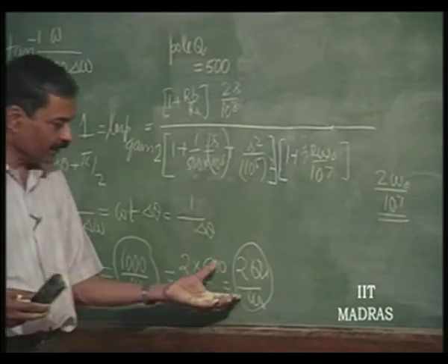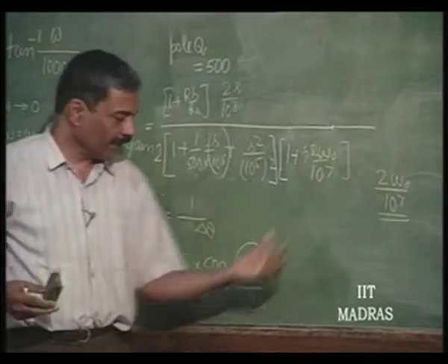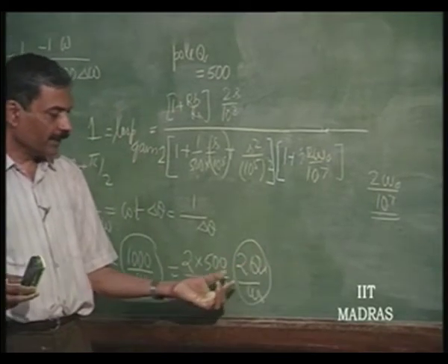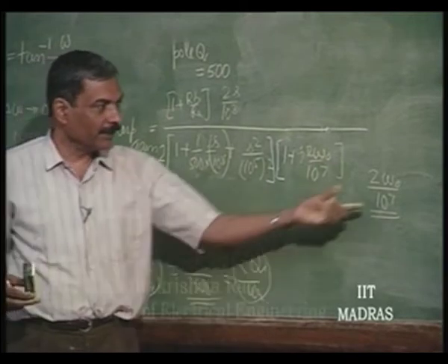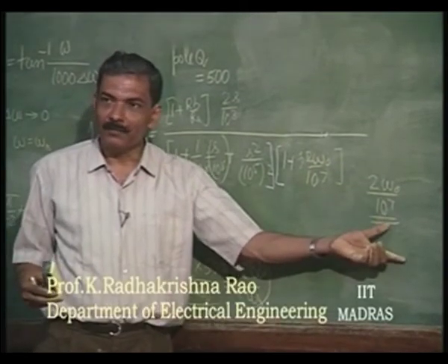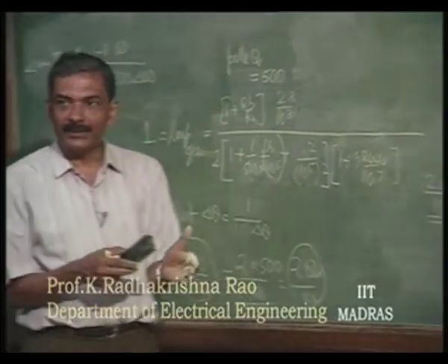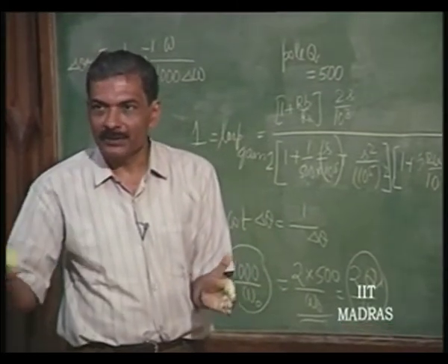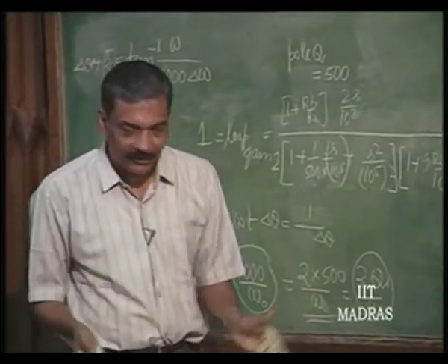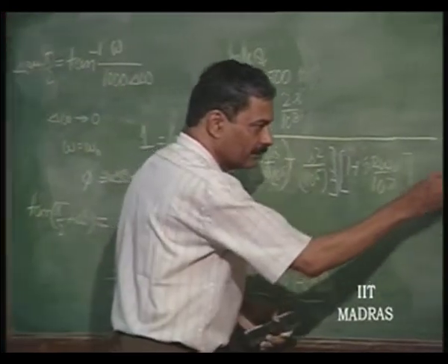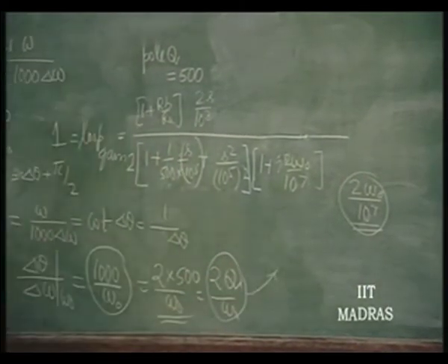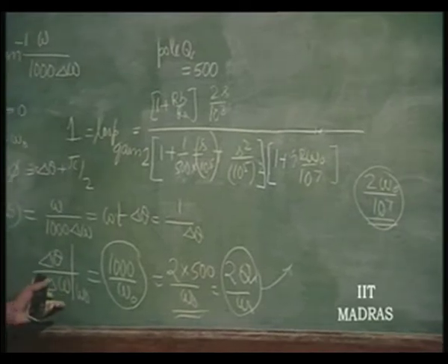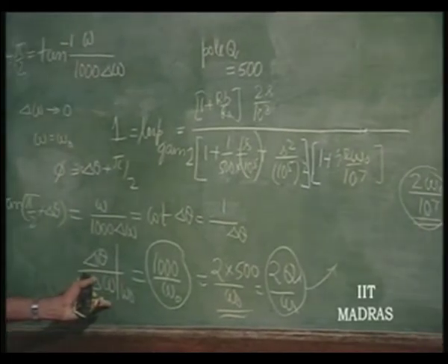So, you will just equate this to this phase error, and therefore, you will see that the actual frequency is going to be different from omega naught by a factor which is determined by 1 over Q. So, this is the phase error. This has to be compensated for by delta phi by delta omega, by delta omega changing accordingly from omega naught.